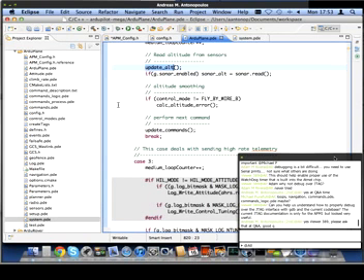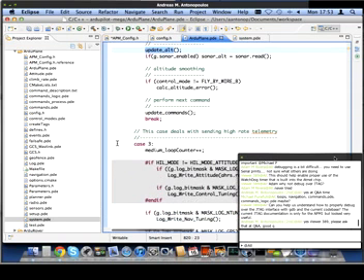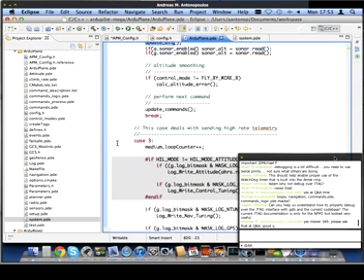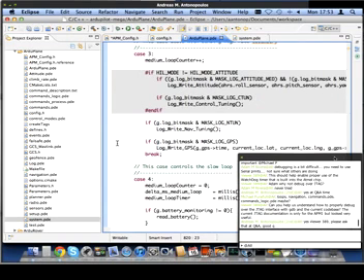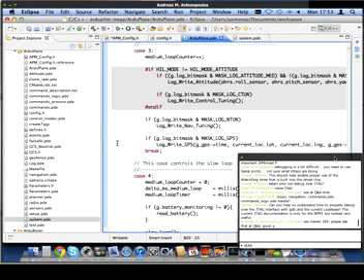And it also helps on the DCM solution calculating the expected vertical acceleration in our discrete cosine matrix attitude solution code. And so it's a little bit misleading there where you see update out called at 10 hertz because you might think our barometer is just 10 hertz when in fact it's running at a 80 hertz pressure rate.